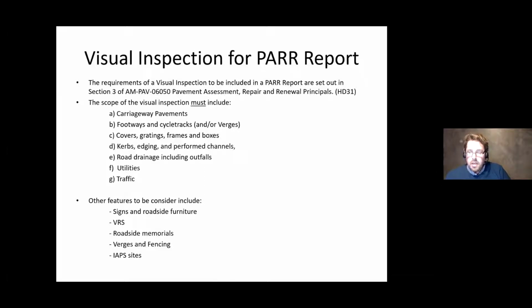So you could be looking at Eir, Bord Gáis, the ESB, the water services, the sewerage systems. You need to be conscious that while you're about to do a nice new pavement overlay job, are the ESB going to come along in 6 months' time and put down a new master line or master cable? So be in contact with the utilities as you go along, as well as getting the mapping from them of where their utilities are relative to your site. What are their plans? Just make sure that you're not being too premature with your works.